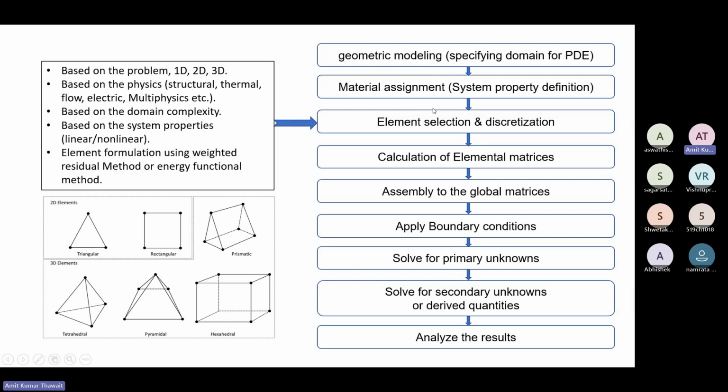Okay, so a number of grid independence studies we perform. So we use different grid sizes, so a different number of elements will be there. Like that, we perform this whole step again, and we analyze our system.